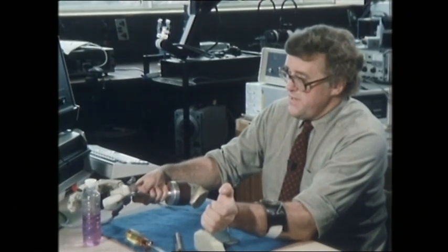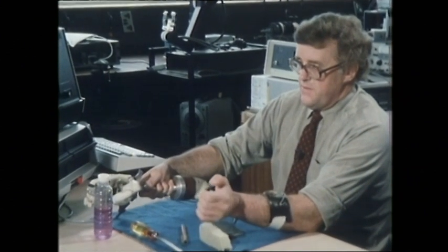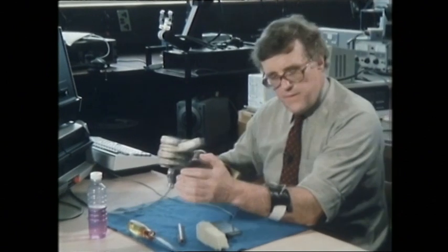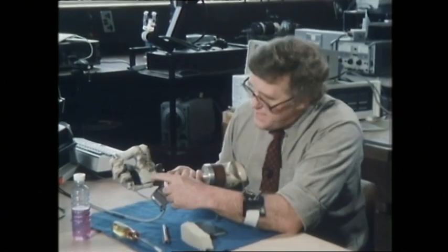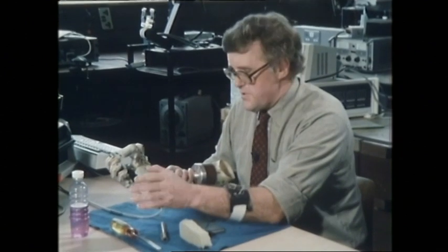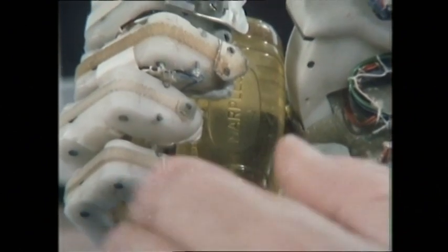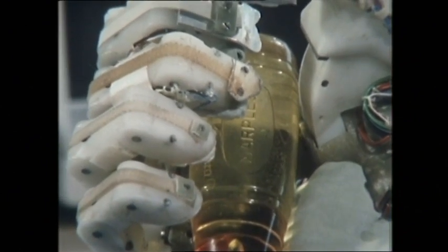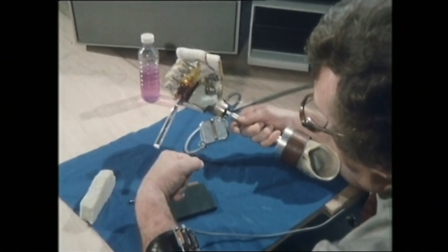And I can close it very gently on something and pick it up and then put it back down again and release it. So there I'm using control, I'm controlling it. But in addition to that, this hand has 10 sensors on the palm, in the fingers and in the thumb, so that it will do things quite automatically outside my control. For example, if I take this screwdriver, I touch that sensor, the hand will automatically position itself to grip it. I then take over command myself and hold, and the fist will close over it.